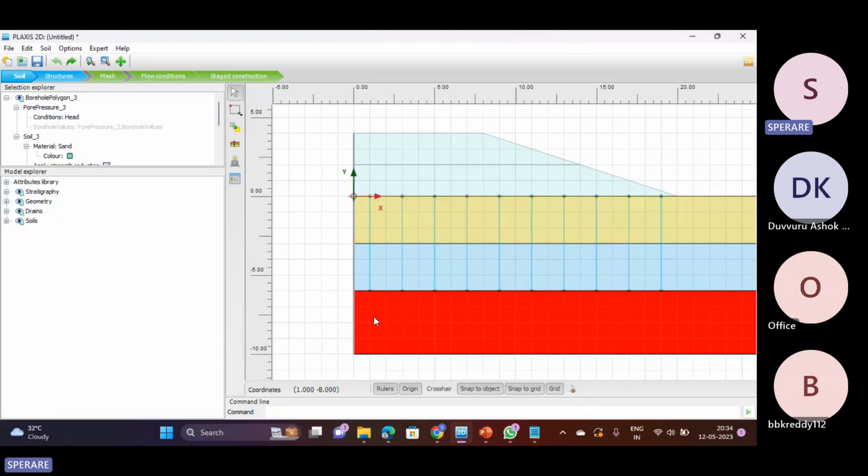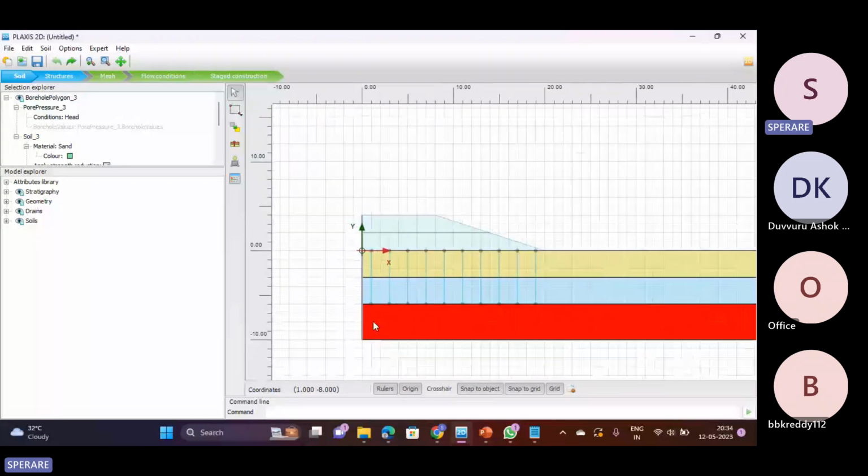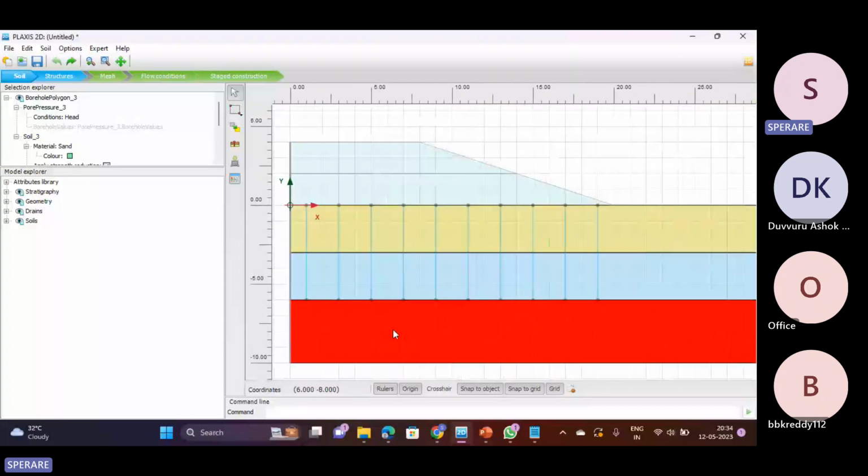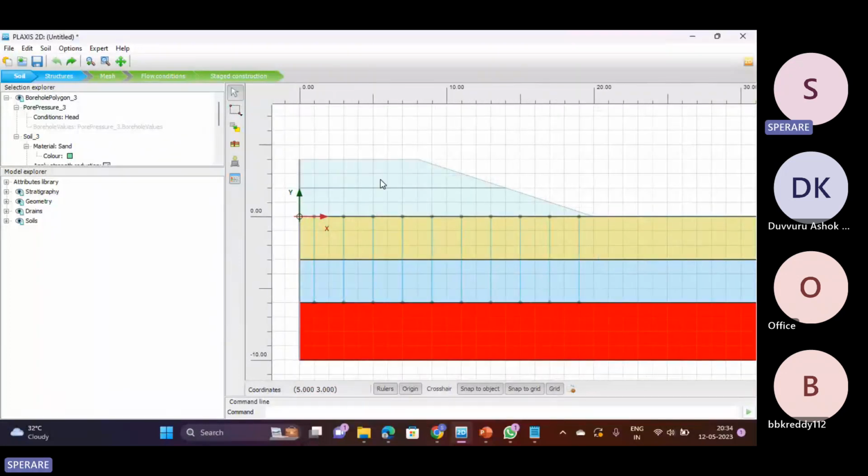So when you are extending the depth of a drain, make sure that the material properties are also supporting you. You can't just blindly go for the depth. Make sure it really needs to be modeled as drained or undrained A conditions. Anyway, the backfilling is a hardening soil which doesn't need undrained A conditions. It's not short term; it's a long term analysis, so it requires drained conditions only.